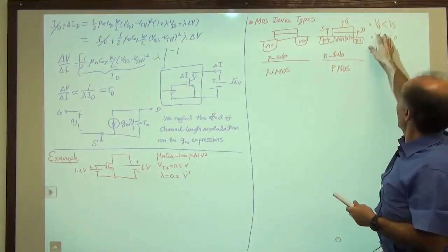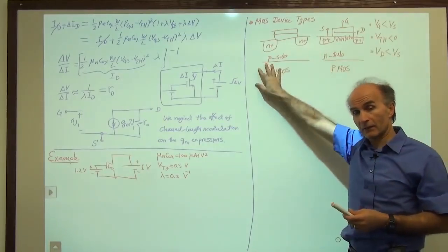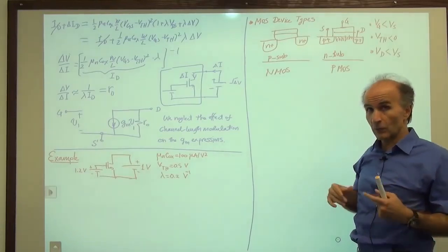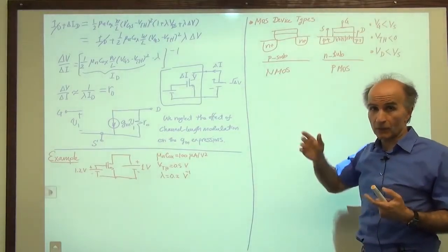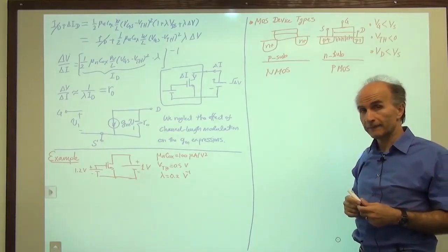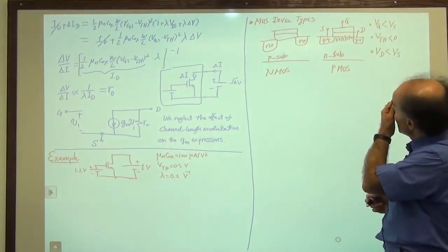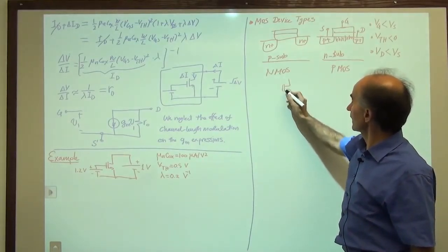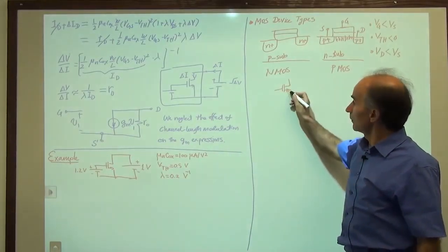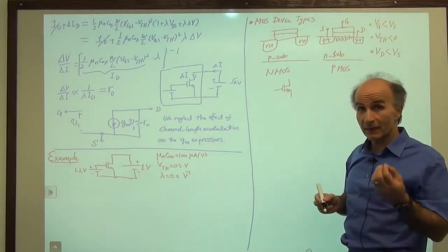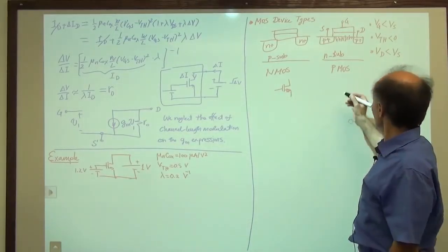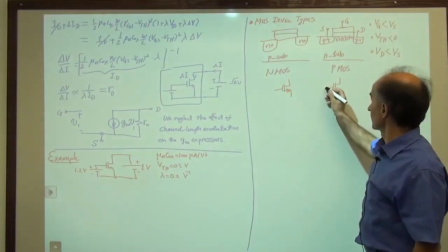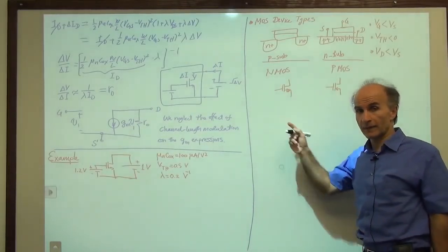Now these values are not as intuitive as what we had in the case of NMOS, but we have to get used to them. In CMOS technology, we use both PMOS and NMOS, so we have to know both of them very well. The symbol for the NMOS device has an arrow pointing outward, representing the source terminal. For the PMOS device, we have a similar situation, except that the arrow points inward. This is how we distinguish between PMOS and NMOS.